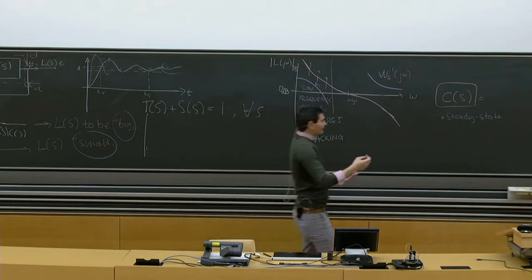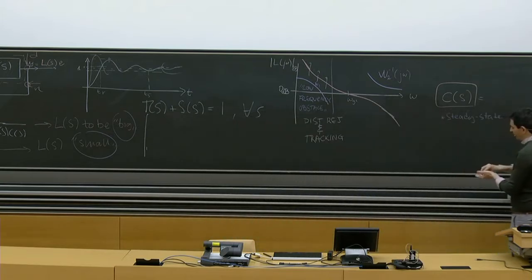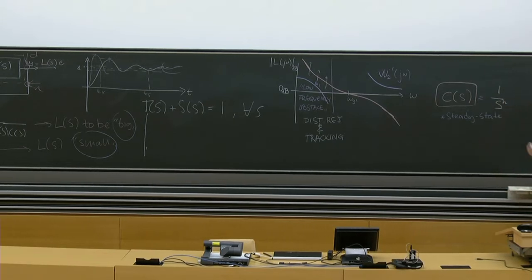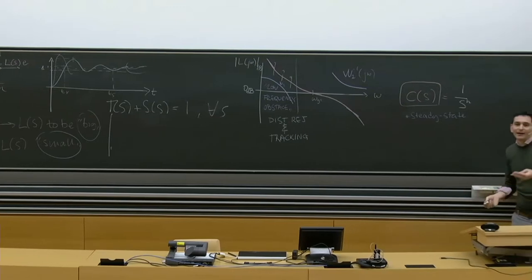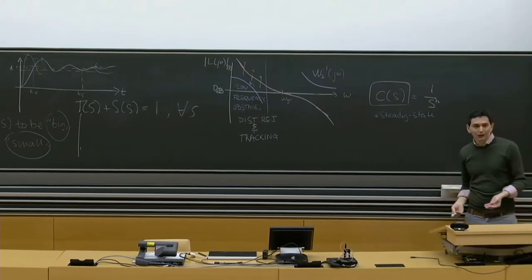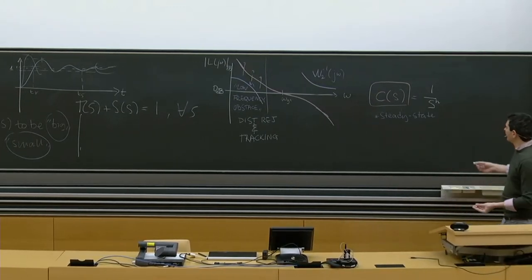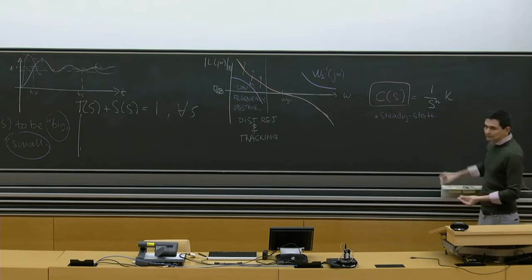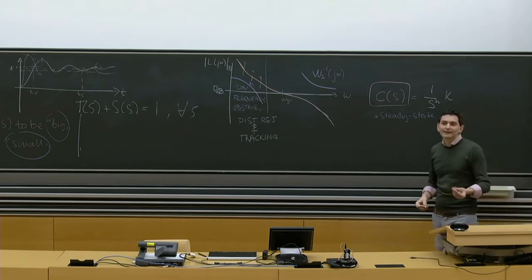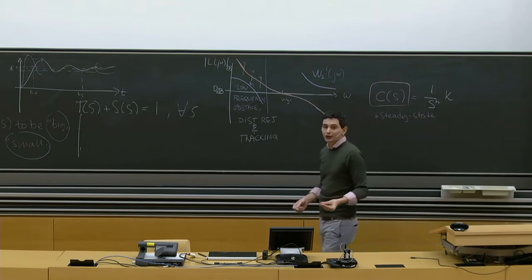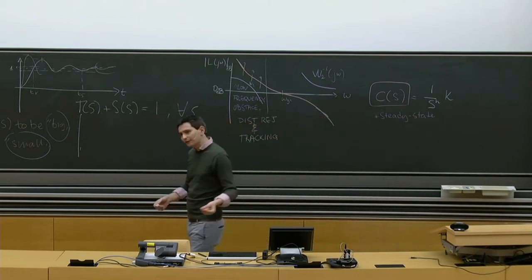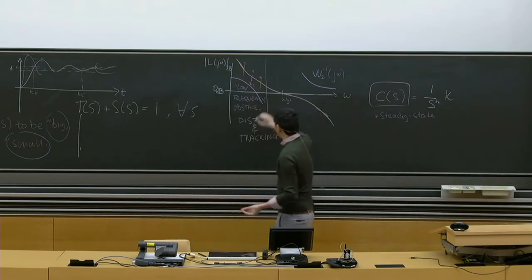So the first thing you do is typically you add a bunch of poles in zero, okay? I don't know how many, I'll just say H, where that H really depends on how many are already there and what are the specifications in the steady state. Then we add a gain to satisfy the specifications always on the steady state, for example, but even on the tracking disturbances.